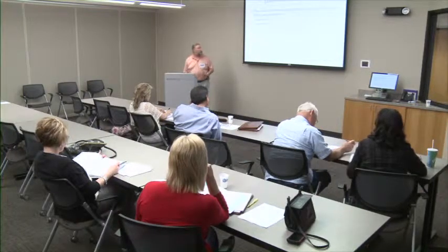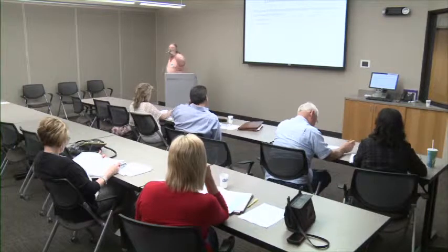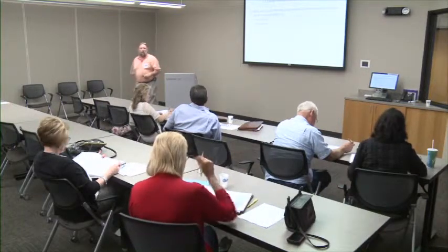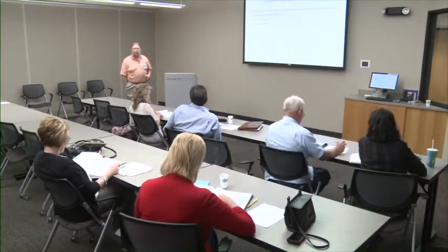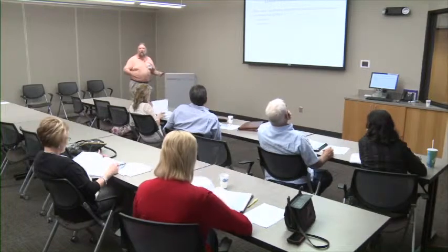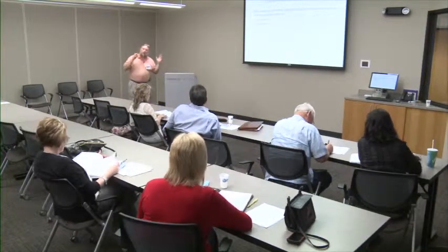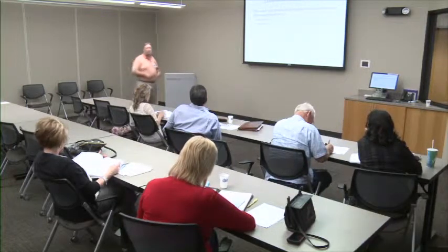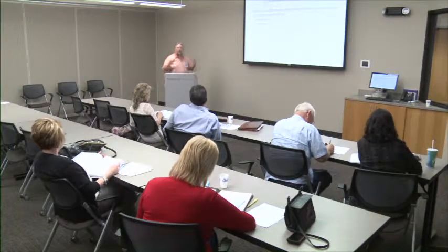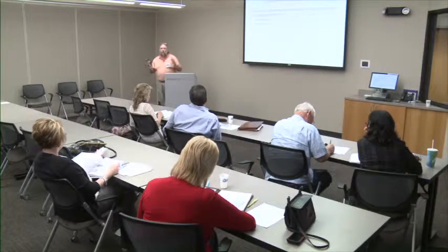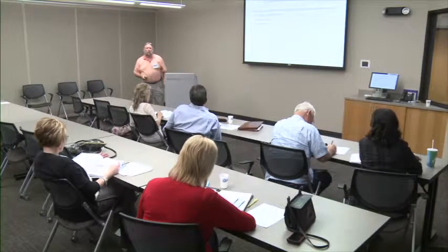Look-ahead scheduling means we want to see what's out there 2 or 3 weeks ahead, maybe 1 month. It's not something where I want a look-ahead schedule for the year. Okay? No, it's short-term only. What's happening next week? What's happening in the next 2 weeks? What's happening in the next month because we're behind schedule and we want to make an adjustment.